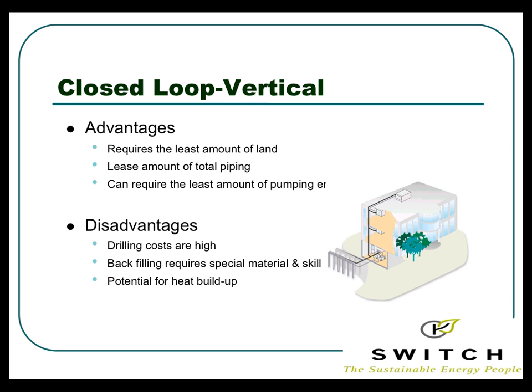Closed loop can be in different types of configurations. First one being vertical, or your borehole, okay? This is the one that you'd see mostly in an urban environment because we have land space restrictions. So we need to go vertically with that closed loop, as you can see in the diagram.